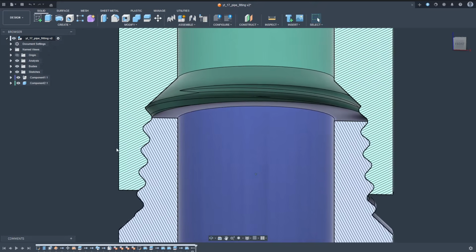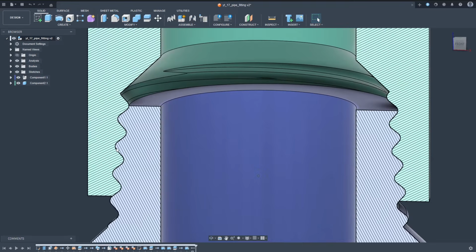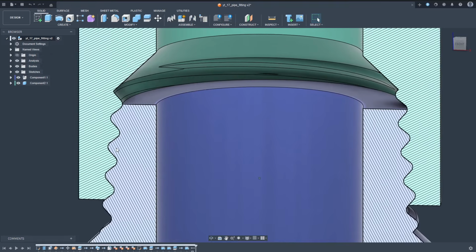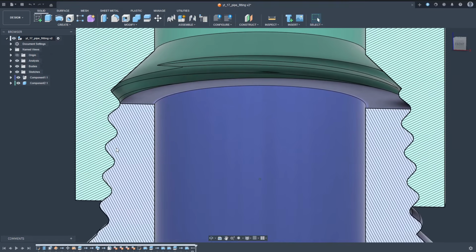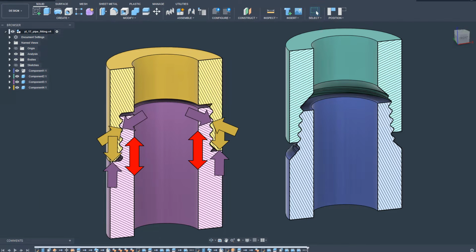In the context of 3D printing, they allow to tightly mount parts without having inner tension in the threaded section, which is not the case for conventional cylindrical threads. I quickly sketched the difference. In the cylindrically threaded design on the left side, the inner part is under axial tensile load, which is typically bad for 3D printed parts, assuming horizontal layer orientation. The tapered threaded part does not suffer from this effect, as the loading is effectively applied in the radial direction.